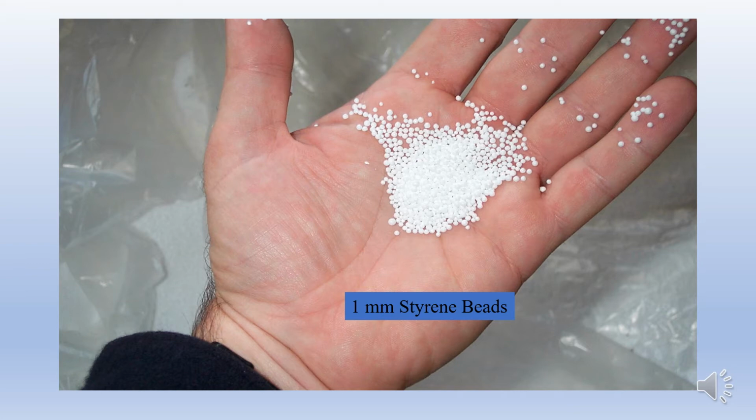This slide might be a little bit before its time, but I just wanted to show you guys what usually happens to all of the suspended solids that are taken out of the system. They'll usually end up in some kind of conditioning chamber where you get the start of bacterial activity on the solids and any of the nitrogen material that's in them. These small beads could have been put in any kind of system, and if you recall, if you've looked at some of those videos that Paul Begay illustrated, he talked about these things. These are little bitty polystyrene beads. They're what is in our bead filter out at the lab, and they're what's helping to convert the nitrogenous waste into something that's not harmful to the fish.